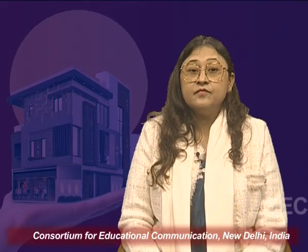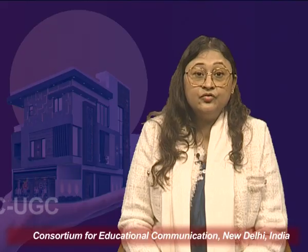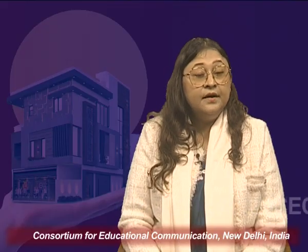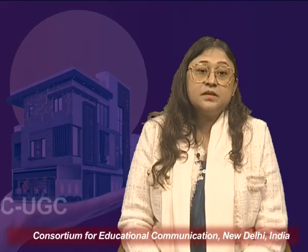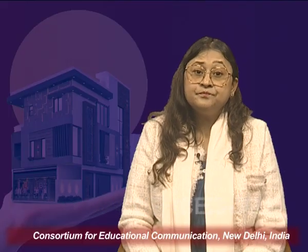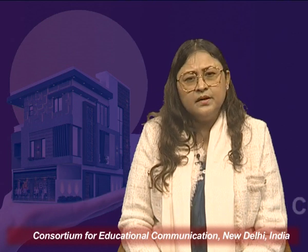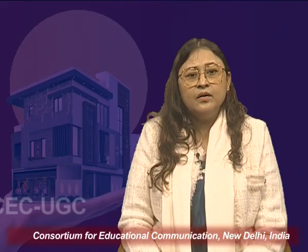The key takeaways from today's lecture are: we understood what the different bylaws are, and how they are local legal tools which ensure health, safety and comfort. We cannot ignore them because ignoring them could lead to congestion, poor lighting, ventilation and risk to health. Plot area, building line and setbacks are all important factors which have to be taken care of while designing, and understanding built-up area, ground coverage, carpet area, super built-up area, FAR and FSI will all help maximize design within the permissible limits.